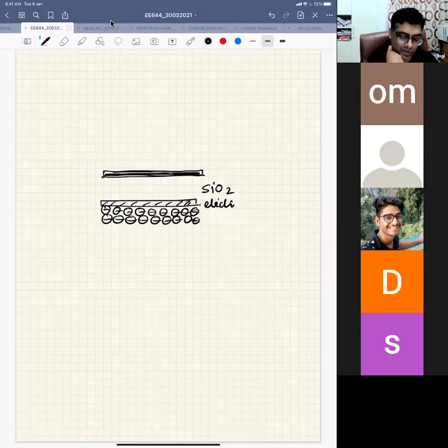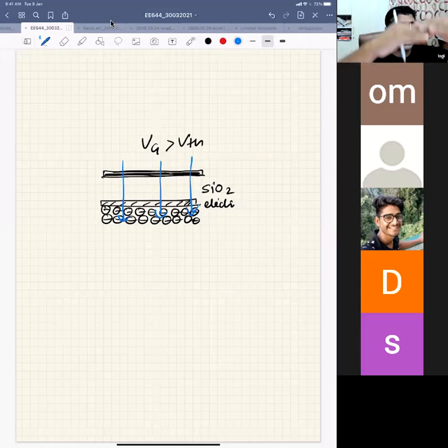Okay. And so the direction of electric field. See, if your VG is positive, let's say in inversion, your VG is more than VT, inversion case. So your direction of the electric field is this direction, but the magnitude of this electric field is increasing or decreasing, right?